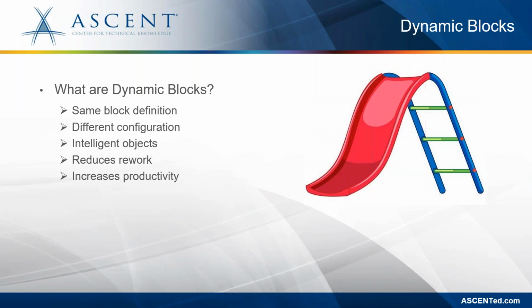A standard block is a single instance of a block, whereas in a dynamic block, we define one instance of the block, but different actions and parameters are added such that you can have the same block in different sizes or different orientations, like you could have a flipping action defined in them. You could also incorporate different visibility states and many other different configurations as well. Therefore, these dynamic blocks, in a way, become intelligent objects which can change as per the parameters and actions that are defined for them.